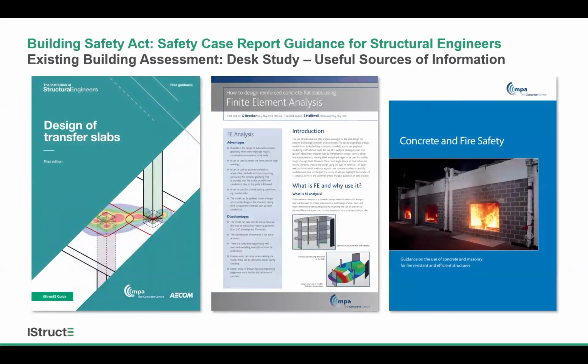Other documents, so the recently issued guidance on transfer slabs, that includes scheme design rules around rules of thumb for how thick a transfer slab would need to be for different numbers of stories, which can be quite useful when you're doing your initial desktop study to see if the sizes seem about right. There's obviously guidance around finite element analysis, concrete and fire safety. So bits of that might be appropriate depending on the nature of your assessment and what you find. And if there are areas that are of a concern, it may prompt a more detailed review.